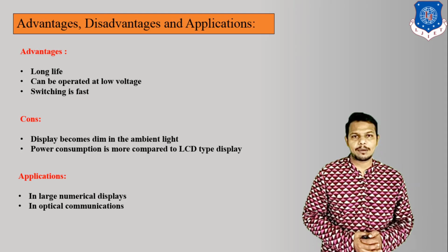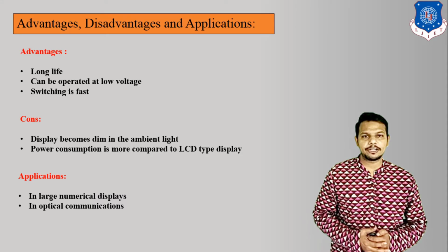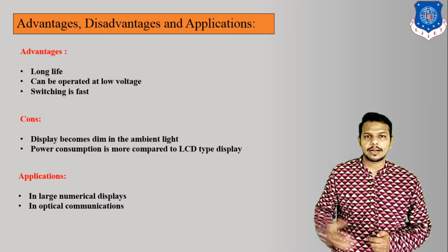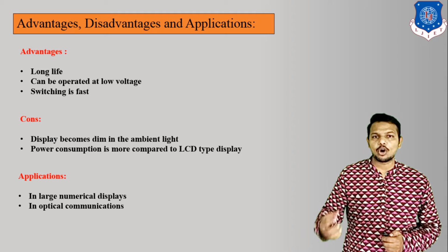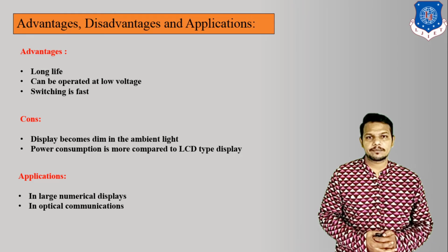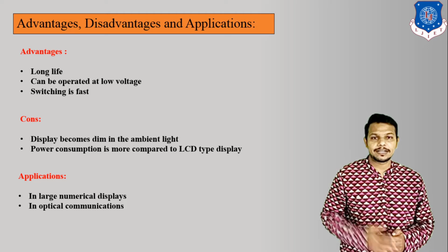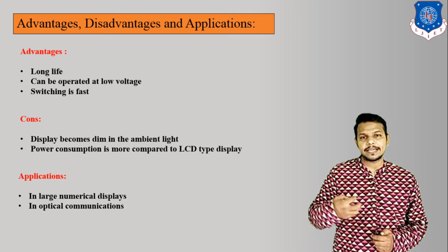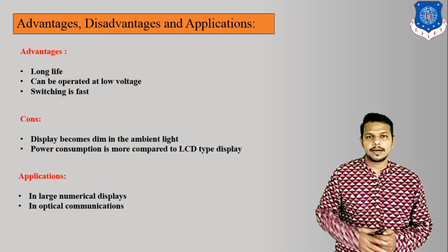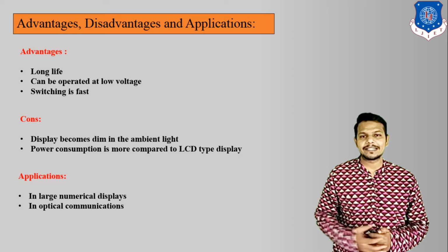Now let us discuss its advantages, disadvantages and applications. First, the advantages: it has a long life. It can be operated at low voltages and switching is fast. So these are the advantages of LED. And disadvantages: the display becomes dim in ambient light and power consumption is more compared to an LCD display.